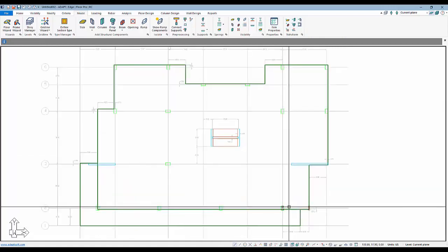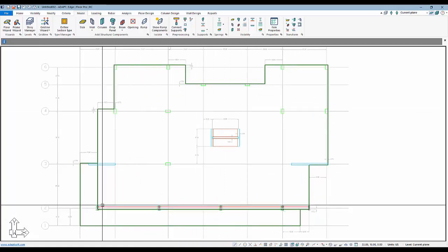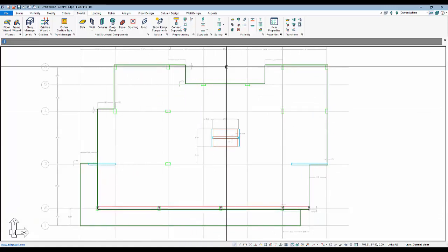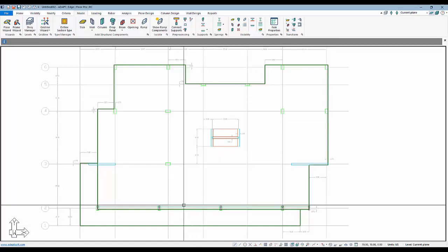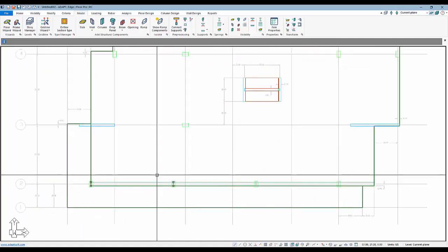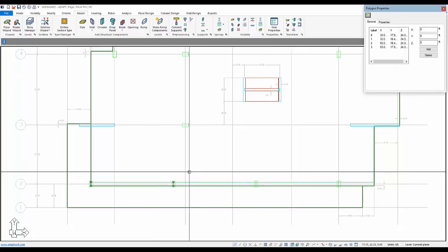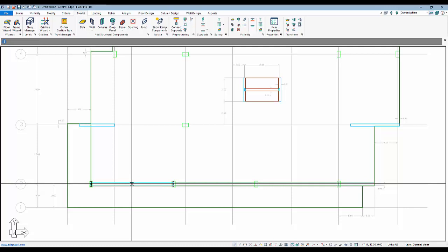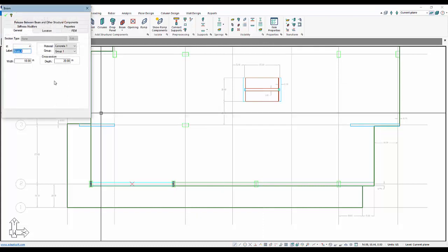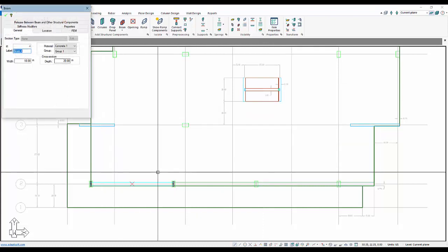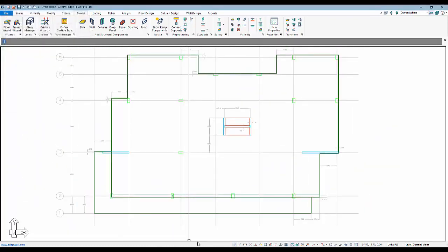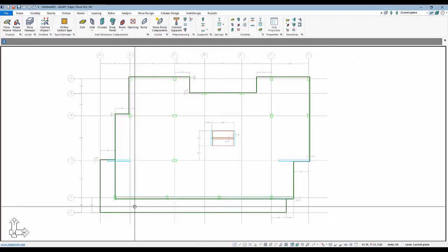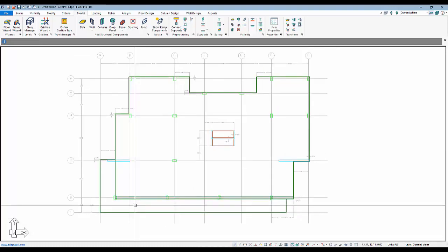And then also we have a few beams here. The program will default to the beam depth. The beam width is based on the actual width of the polygon. I'll transform that over to beams. Again, if I double click, you'll see this will actually open the properties of the polygon. So if I select once and then press Tab, it will toggle back to the actual beam element that I had just transformed. And now I can go to properties and define a depth if needed here, or we can do that after we've finished using the CAD file, the DWG file, to transform.